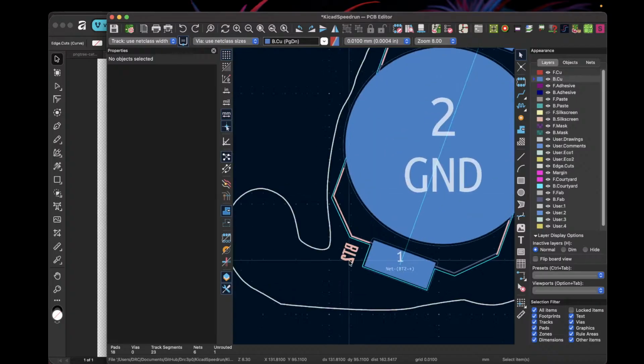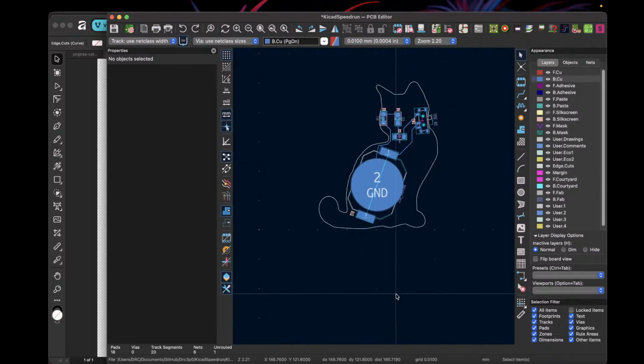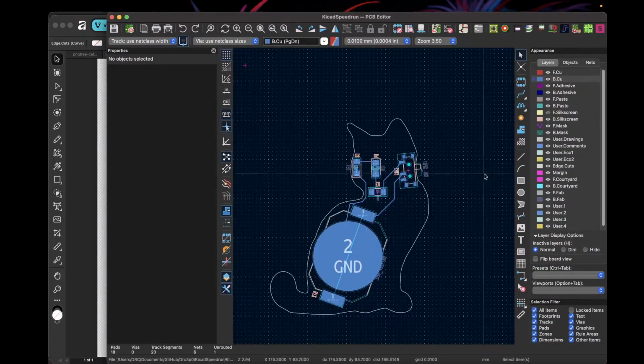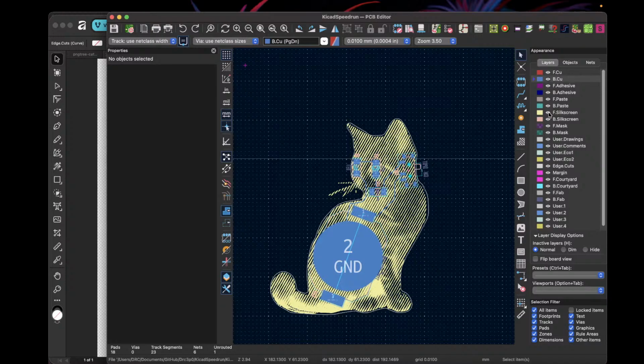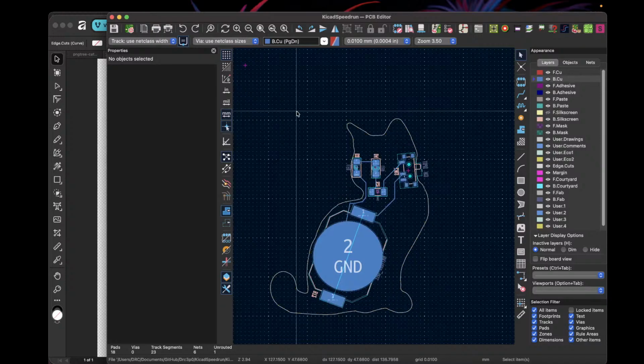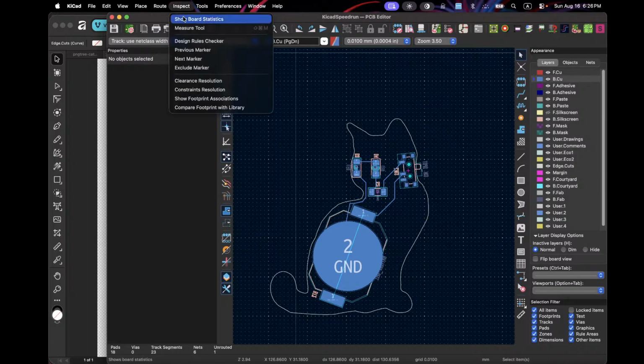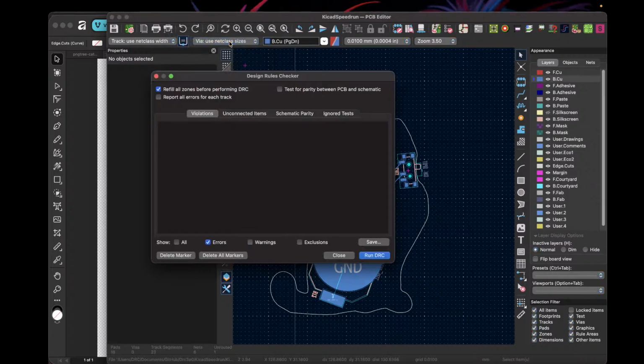We've moved that to somewhere that's visible, save our work. And in theory, this is a circuit board that we can order. But before you order a board, I always recommend you use some of the built-in sanity check tools to make sure that you've wired everything up. Because once you get a complex board, it's super easy to forget that something hasn't been wired yet.